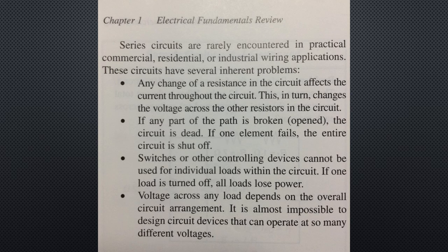Series circuits are rarely encountered in practical commercial, residential, or industrial wiring applications. These circuits have several inherent problems. First, any change of a resistance in the circuit affects the current throughout the circuit, which in turn changes the voltage across the other resistors in the circuit. Second, if any part of the path is broken or opened, the circuit is dead from that point on. If one element fails, the entire circuit is shut off, or at least part of it.